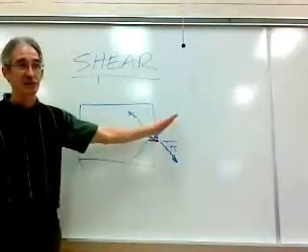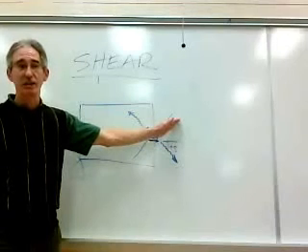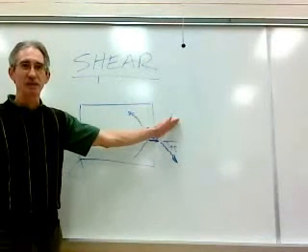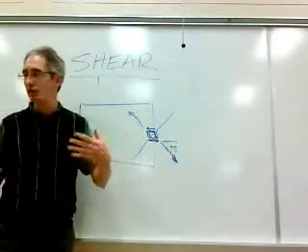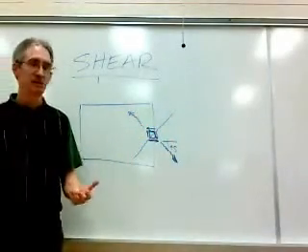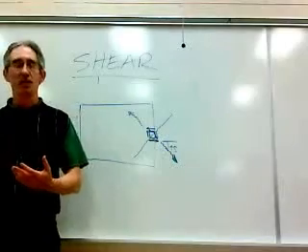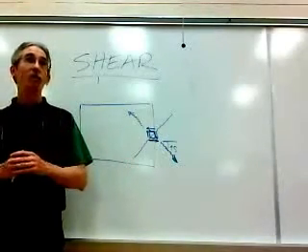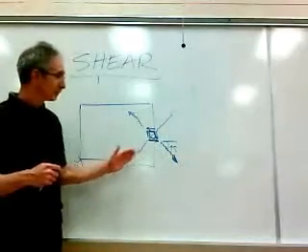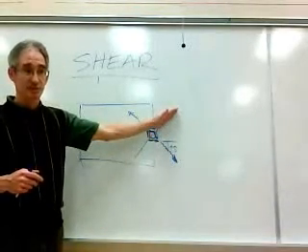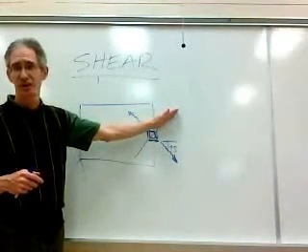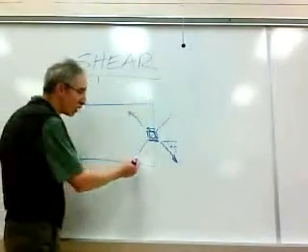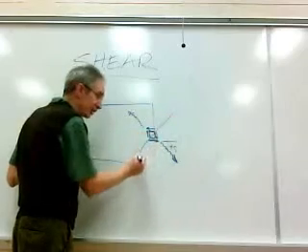Shear cracking is not like bending cracking. Bending cracking is going to take place because our beams are supposed to be ductile. Bending cracking is going to take place, if it's a ductile beam, in a slow, progressive manner. A shear crack, if it occurs, is going to occur very quickly. And it literally will run on a 45-degree line.